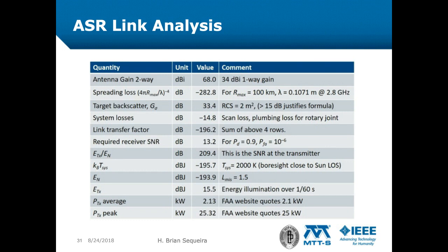This example serves to illustrate application-induced coupling of radar variables, such as coverage, revisit time, and angular resolution, which have coupled detection time, range, and losses. It further demonstrates that the formalism developed from energy considerations leads to accurate prediction of the transmitted RF power required to accomplish detection.